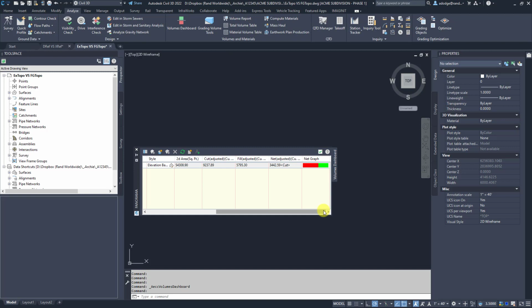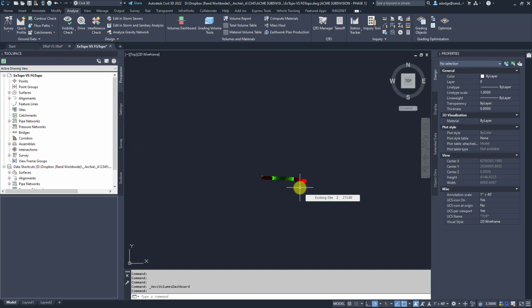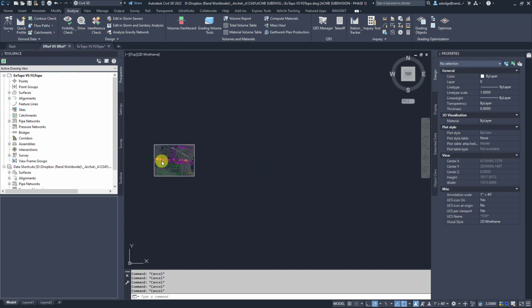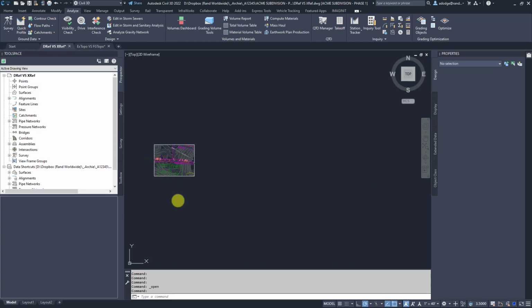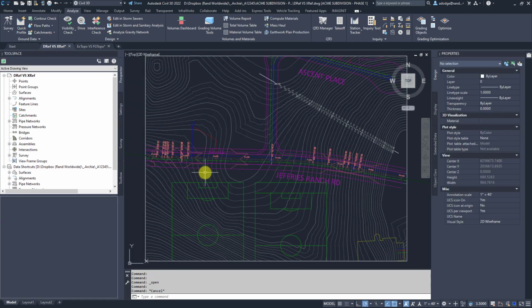Now when it comes to Civil 3D, breaking these things down into their dedicated drawings will help you out when it comes to processing things like that. So eliminate as many crashes as you can by keeping everything kind of dedicated into their own drawings. So as a recap, just remember, if all you need to do is show it on plan view, XREFs work out just fine.